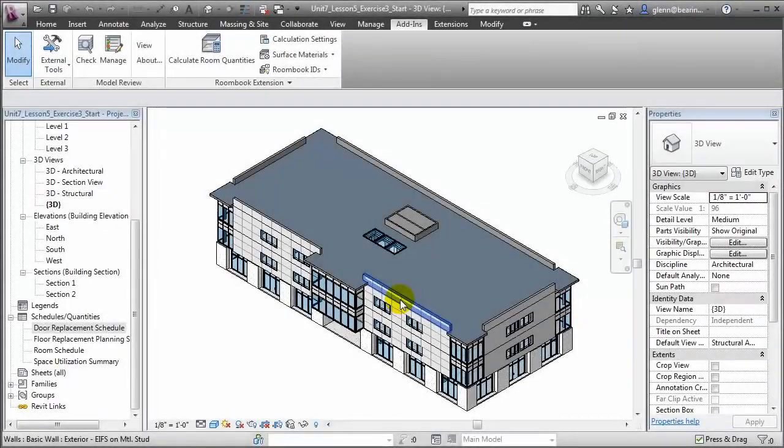When the export is complete, the Link Revit Model dialog closes and we can return to working with our project model in Revit. Let's instead switch to Microsoft Access and look at how we can edit the parameter values for those doors directly in the database environment.